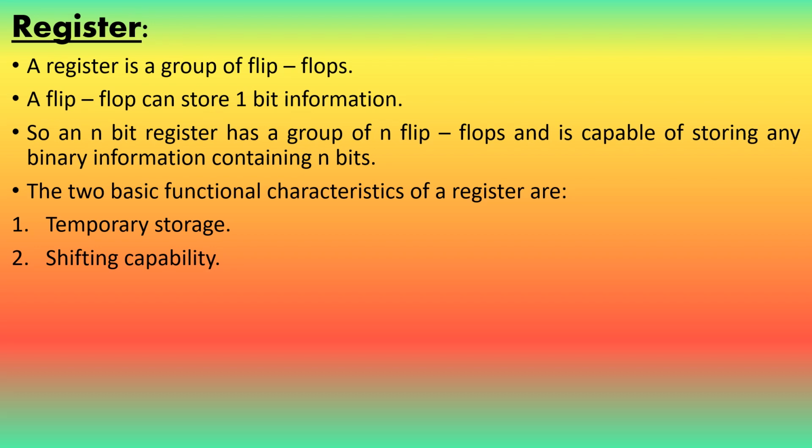Register. A register is a group of flip-flops. A flip-flop can store 1-bit information. So, an n-bit register has a group of n flip-flops and is capable of storing any binary information containing n bits. The 2 basic functional characteristics of a register are temporary storage and shifting capability.